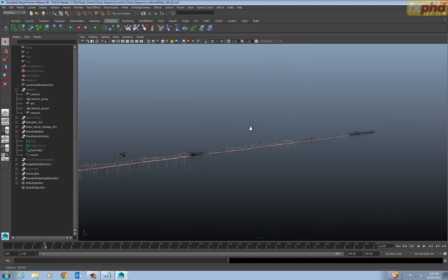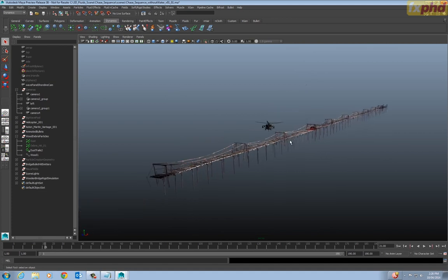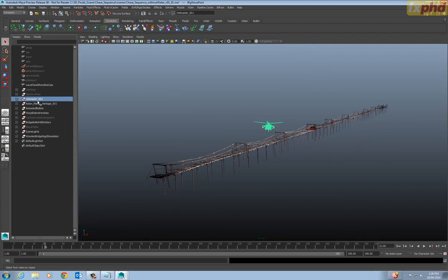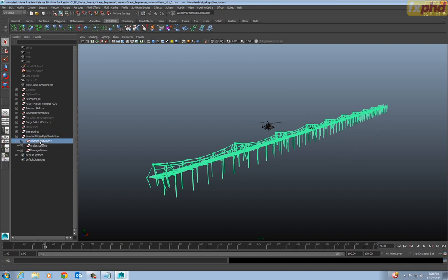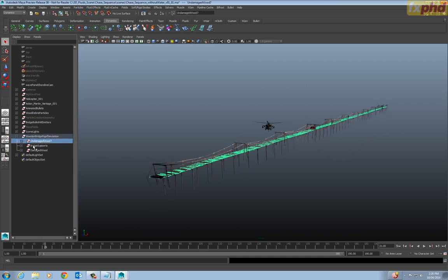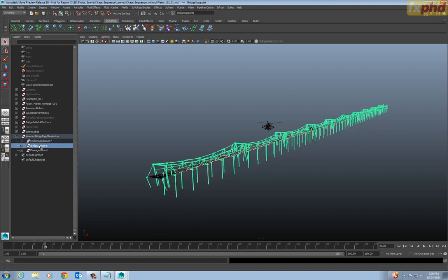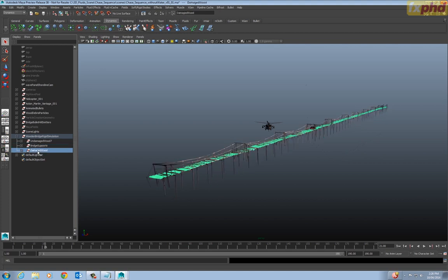How I did my test scene was, after seeing the awesome beach sim that they set up in the Bifrost examples, I basically brought in one of their example scenes and adjusted the properties on the water to get explosive splashes from the bullet impacts. When they were first set up, it was too sticky, so the water wouldn't fly apart into spray.